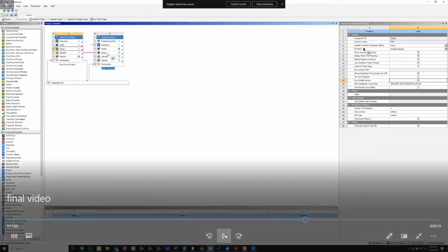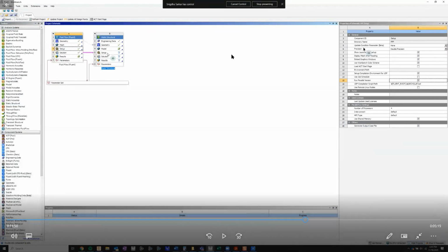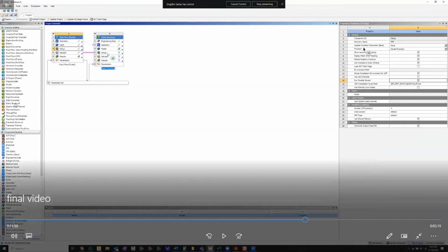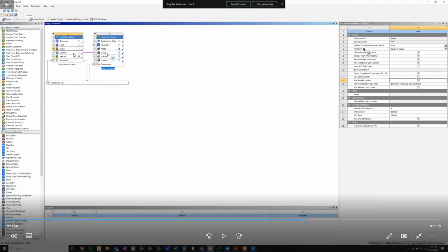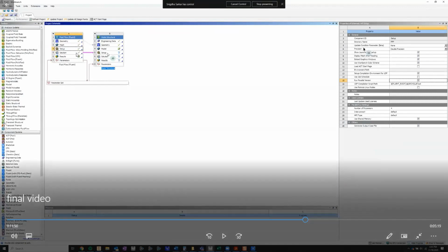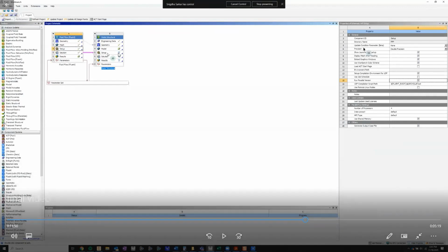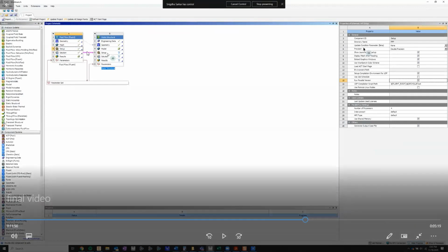And I'm just going to pause right here because this step was a little fast. So what we did was simply drag and drop a static structural analysis onto the solution cell, which is cell A5 of the CFD setup. What that does is it automatically creates a connection between the solution from CFD to the setup on the FEA side, right? And this link is important because we're going to be mapping the fluid pressure as an input load for our FEA analysis. And once you do establish that connection, the geometry part is automatically carried over.